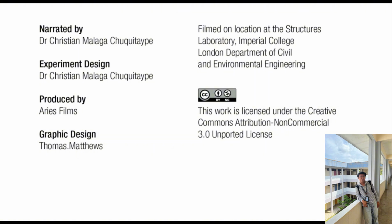That was it for me. Now we'll talk about the lab test on timber. The lab test on timber is the moisture content test. It is a procedure to determine the amount of water present in the wood, expressed as a percentage of its oven dry weight. This is a critical measurement because moisture level affects the wood's stability, strength, durability, and machining properties, with incorrect moisture content leading to issues like warping, cracking, or fungal decay.